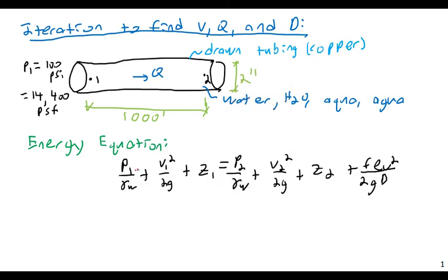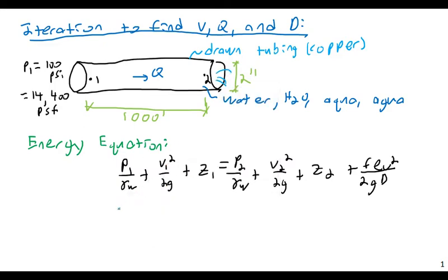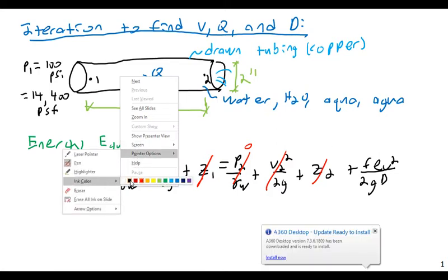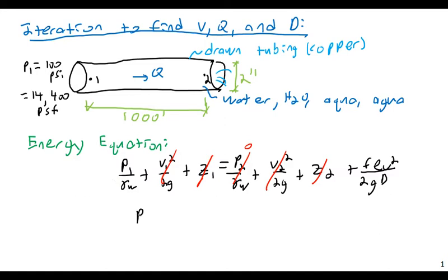Let's say also this is emptying into the atmosphere. It's just a free surface, emptying out of the pipe. So I know then that P2 is equal to 0, so that term goes to 0. The velocities are not 0, but they cancel out because there's a constant diameter pipe, so there must be a constant flow rate, and thus a constant velocity via continuity. And then it's a horizontal pipe, so the elevation terms cancel, and this can collapse to P1 equals f L V squared.